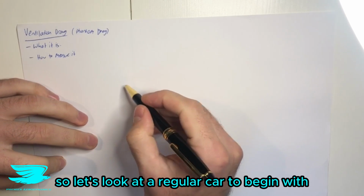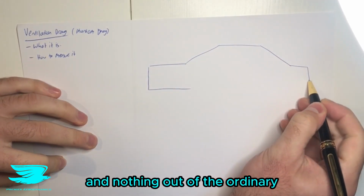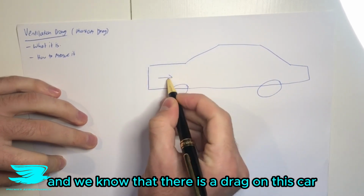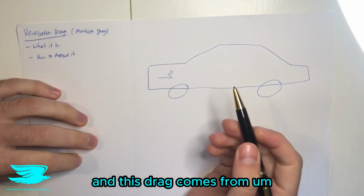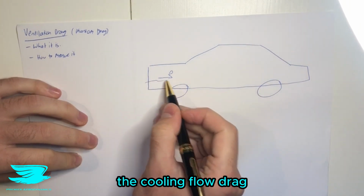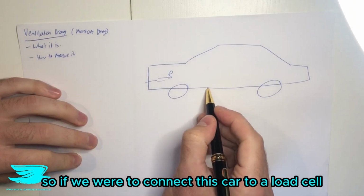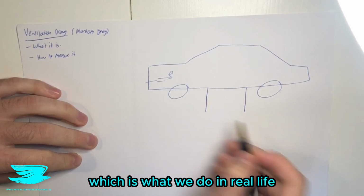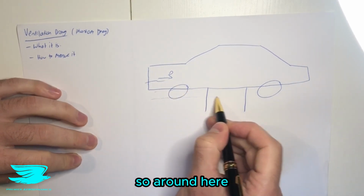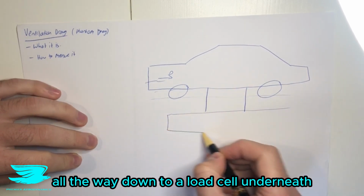So let's talk about a regular car to begin with. Let's say we have a regular car here, and nothing out of the ordinary. We have some wheels, and we know that there is a drag on this car, and this drag comes from friction drag, pressure drag, vortex drag, induced drag, the cooling flow drag, a bunch of other things. So if we were to connect this car to a load cell, which is what we do in real life, we put it into a wind tunnel, and we have the regular floor around here, and then we have struts connecting the car all the way down to a load cell underneath.